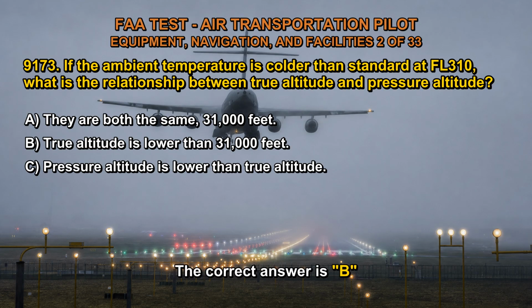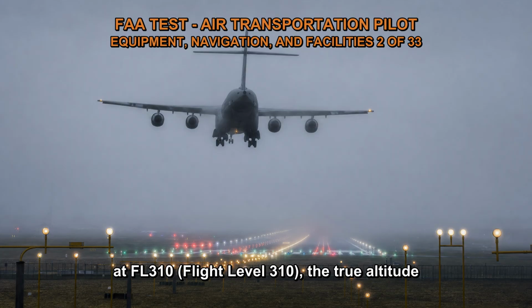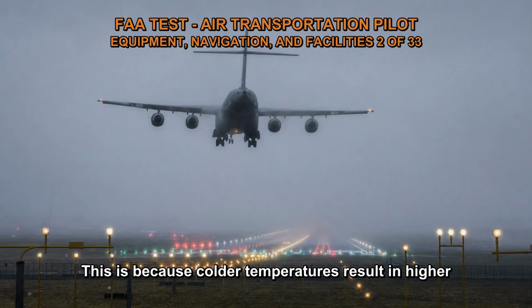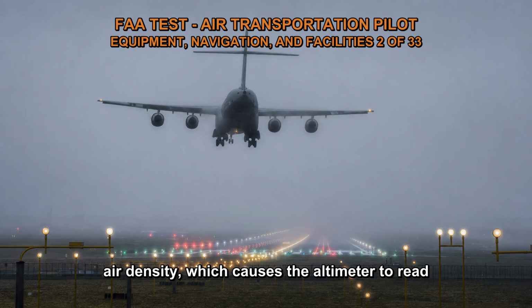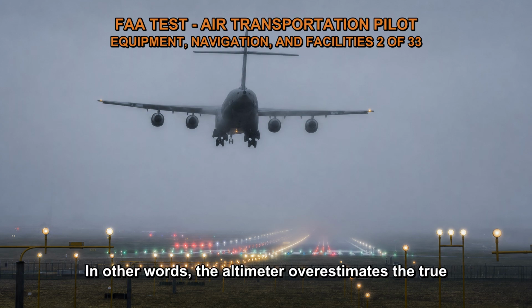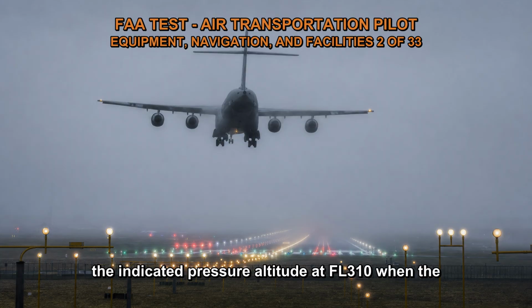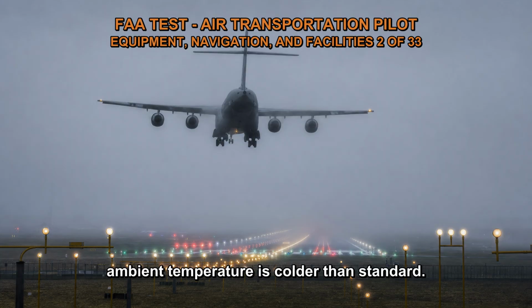The correct answer is B. If the ambient temperature is colder than standard at FL 310, flight level 310, the true altitude will be lower than 31,000 feet. This is because colder temperatures result in higher air density, which causes the altimeter to read higher than the true altitude. In other words, the altimeter overestimates the true altitude in colder temperatures. Therefore, the true altitude will be lower than the indicated pressure altitude at FL 310 when the ambient temperature is colder than standard.